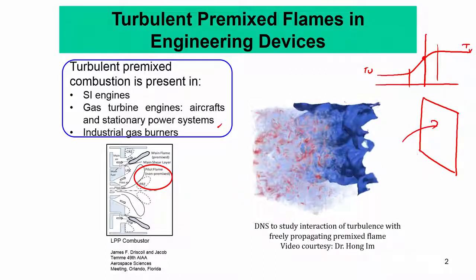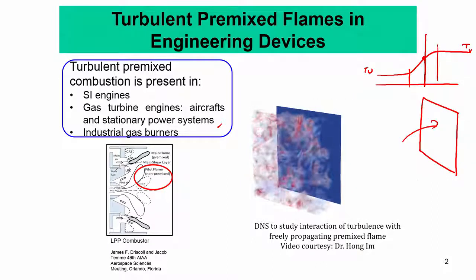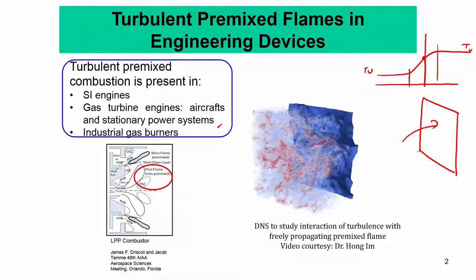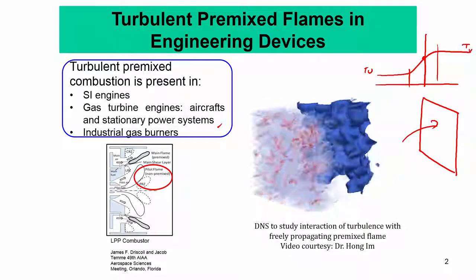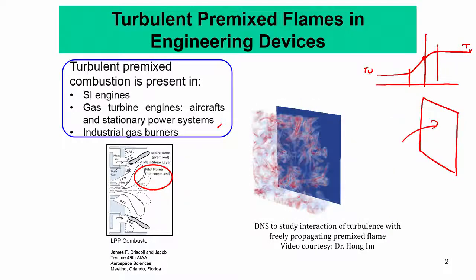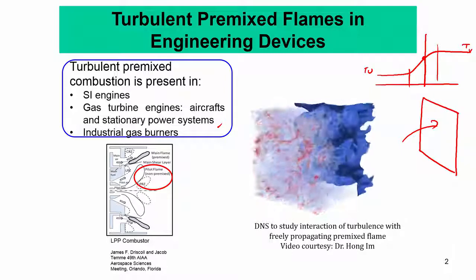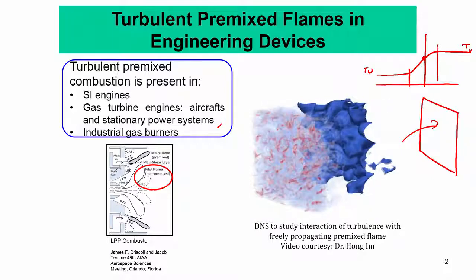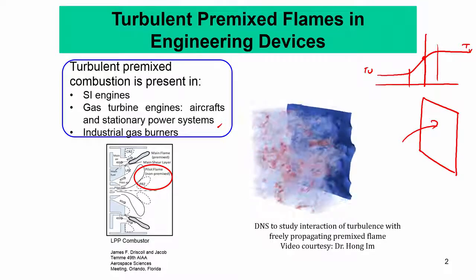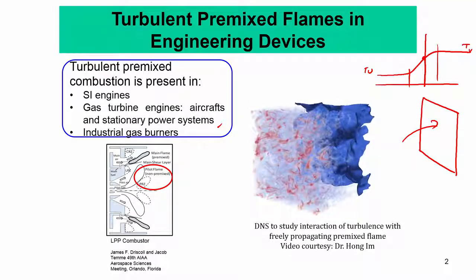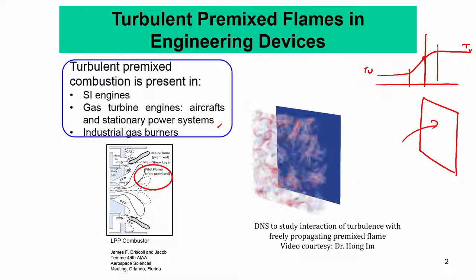Now, this turbulence comes on it and impinges, and it creates different things. But what this does, you see the different vortex, this is actually a beautiful visualization of the turbulence also. This is essentially the vorticity structures, these fine scale vorticity structures that are forming on the premix flame. So, you see that in this premix flame, as soon as it impinges on this surface, it essentially folds and wrinkles the surface at a multitude of length and time scales.